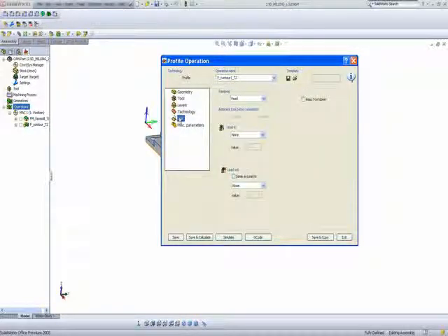Now, my link, in my lead-in, I'll again choose my option of arc. Now I have excess material on this side, so I'll leave this at, let's say, 5mm value for lead-in of the arc. In other words, 5mm from here to here. And my lead-out, I'll use the same as I've done in my lead-in.